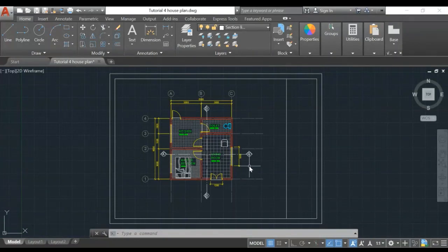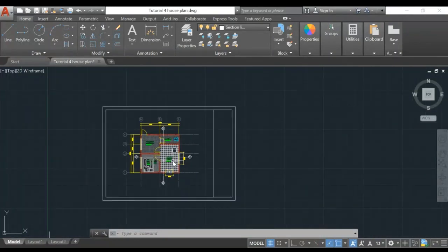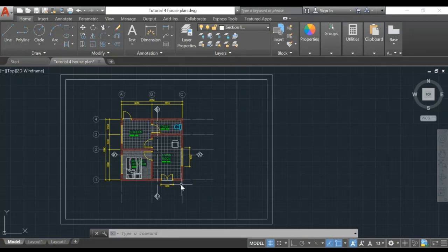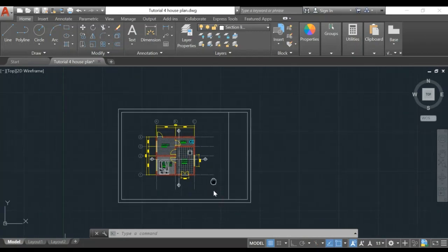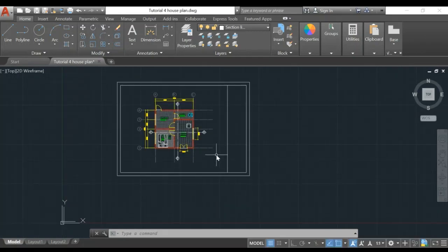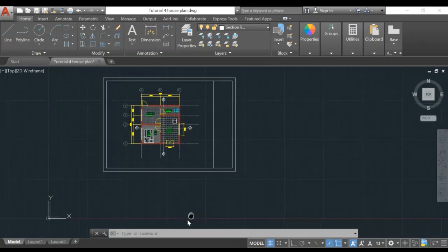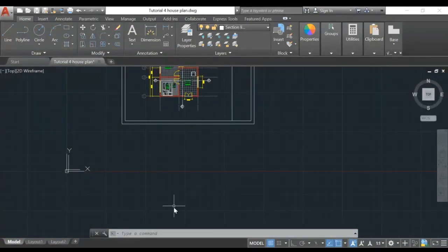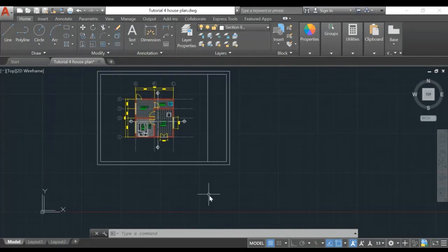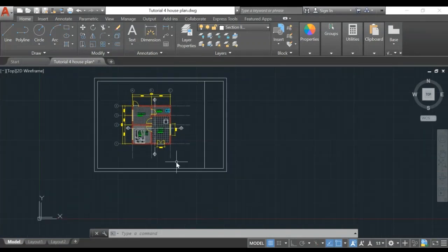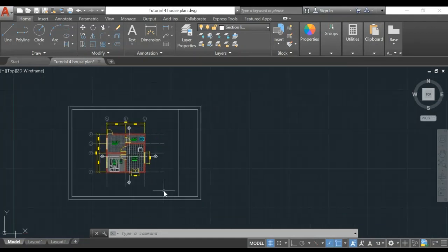After we have completed the section line, it's about time to draw the section drawing, which is the view of the inside of the interior. You have learned from the orthographic drawing project where you extrude the line from the plan or elevation to have another drawing. So you can extrude into a section by extruding from the plan. But there's another way if you're using AutoCAD: instead of extruding from the floor plan you have here, you can just copy this.